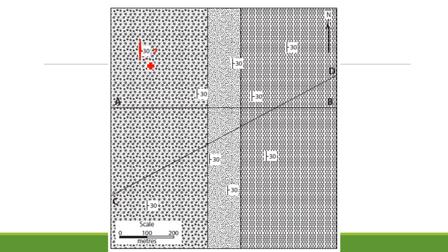And the angle that it's dipping at is 30 degrees. So all of these beds are dipping at 30 degrees. There's lots of strikes and dips. The reason we have lots of strikes and dips on here is because a geologist has walked across this ground and they've measured the bedding in multiple locations, and wherever you measure the bedding you draw it onto your map. So he's measured it in several places on each bed.